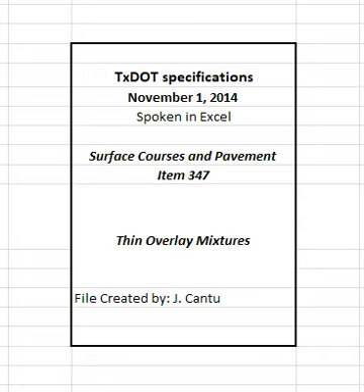4.3.3 Production. For production, include loader operation procedures to avoid contamination in cold bins. Procedures for calibrating and controlling cold feeds. Procedures to eliminate debris or oversized material. Procedures for adding and verifying rates of each applicable mixture component, for example aggregate, asphalt binder, lime, liquid anti-strip, WMA. Procedures for reporting job control test results, and procedures to avoid segregation and drain down in the silo.